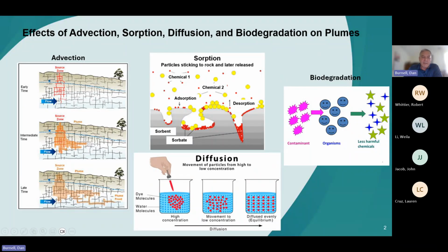As part of that, we have different speeds and velocities that the groundwater moves, and that causes some dispersion of the contaminants to form the plume, and we call that hydrodynamic dispersion too. Another important mechanism for contaminant fate and transport is adsorption.